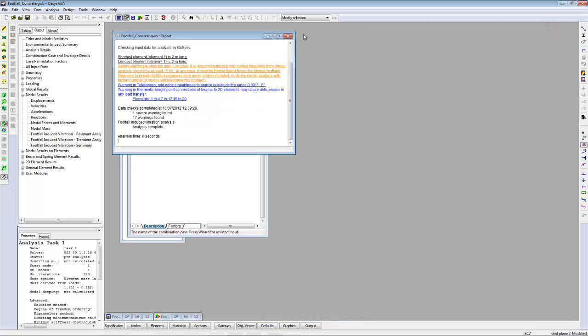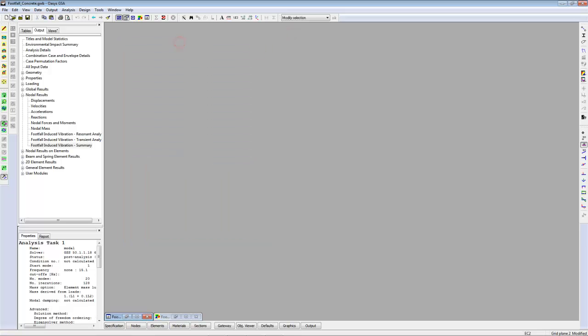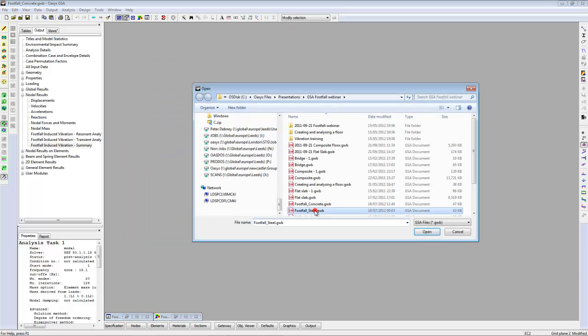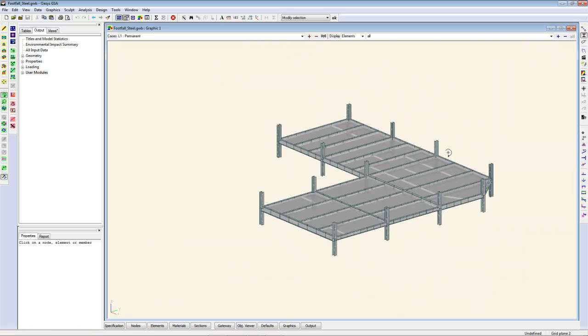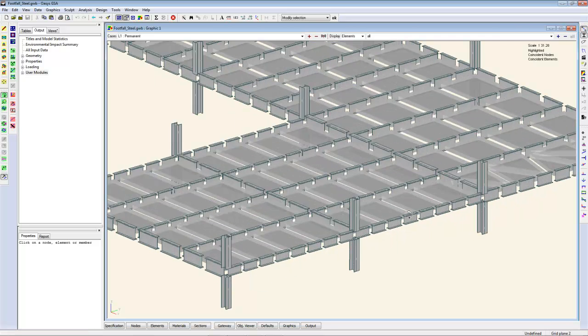How about something a touch more complicated, which is a steelwork model? Now, this steelwork model is already broken down, and you'll note that because the calculations are all done at nodal locations, including the massive lumps at the nodal locations, I've broken each span down into 8 pieces, so we get sufficient density of nodes where the calculation is carried out.